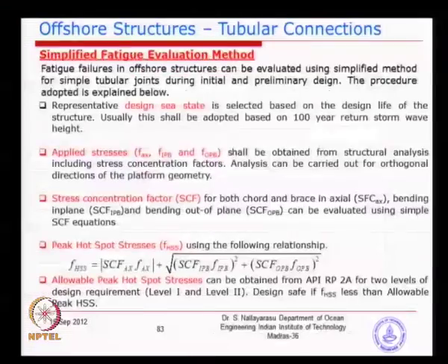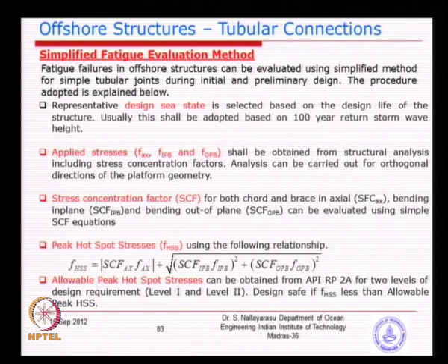So, you will see that this procedure is quite simple. You do not really need to look at the number of cycles, you do not need to look at the stress history over a period of time. What you are looking at is a design sea state: calculate the stresses, calculate the simple stress concentration factors using the simplified formulas, obtain the peak hotspot stress, and then compare that with the allowable hotspot stress as proposed in the API for level 1, level 2 for different water depths, 40 and 100.